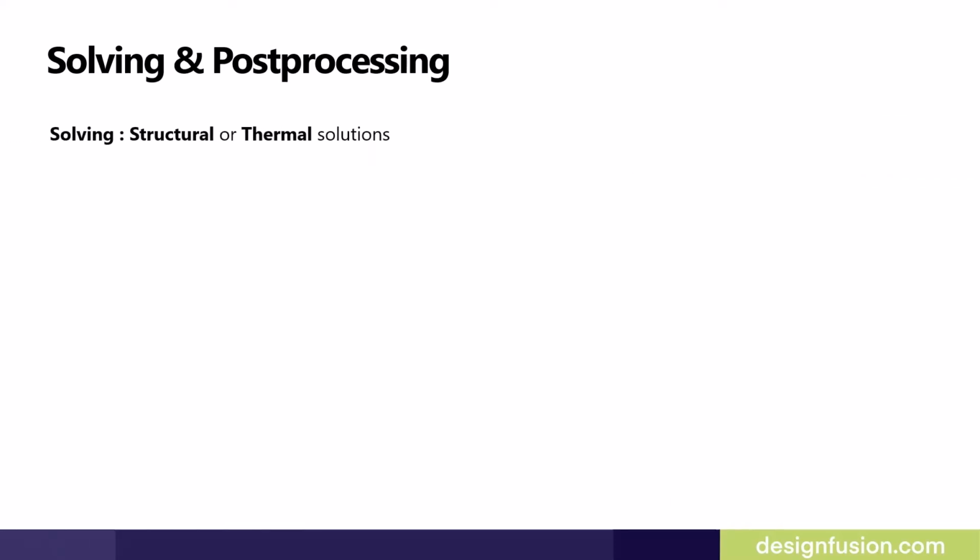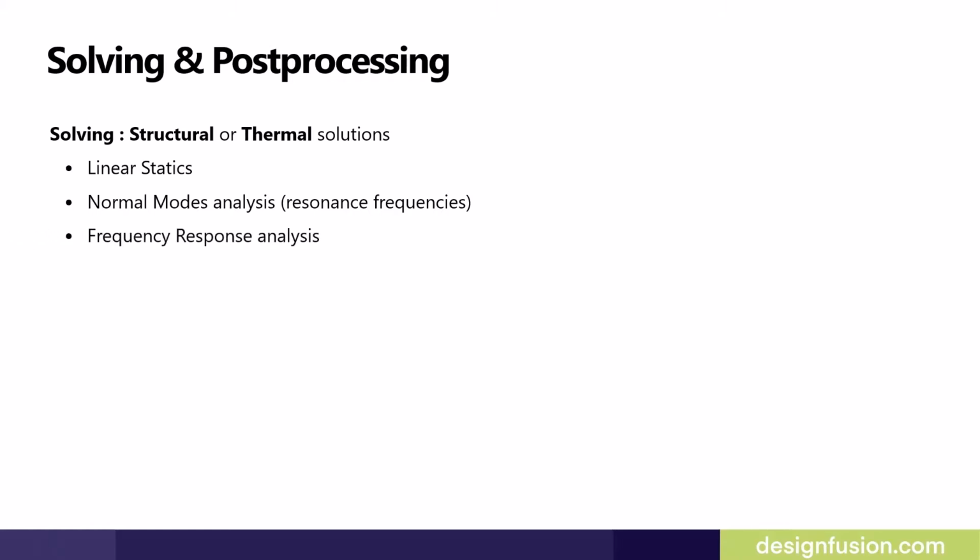So in Simcenter we have different types of solutions such as structure and thermal. If we want to check the structural performance of our product, we can do linear static analysis. If a person wants to check the resonant frequency, they can perform a normal mode analysis. The person who is dealing with an NVH type of problem can do the frequency response analysis.